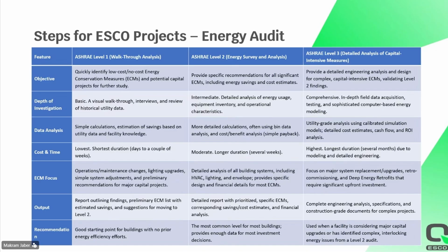For ASHRAE level 2, in this case, we go into more detail in the audit. We will gather more detailed information about each type of equipment. We can do some measurement at this level. We do a lot of calculation. We do estimates, cost benefit analysis.